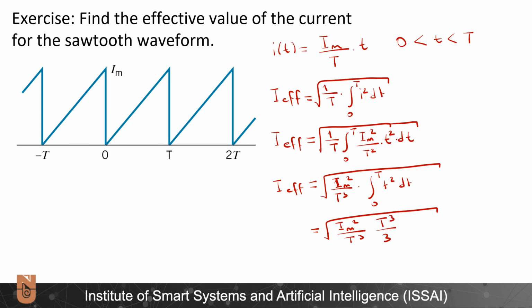I took that integral already, and accordingly if these terms cancel each other, I end up with, for I effective, Im divided by square root of 3.